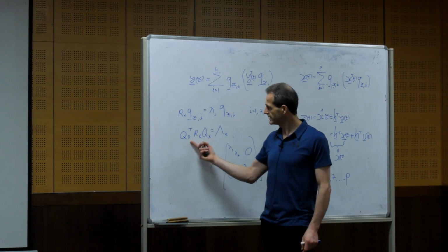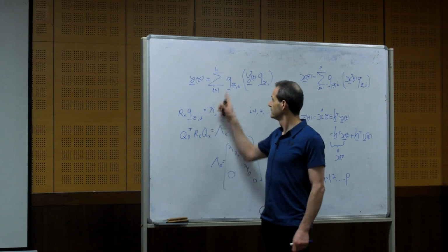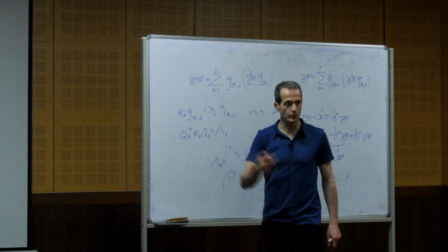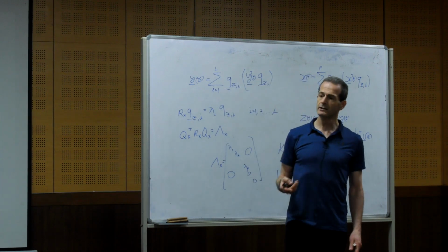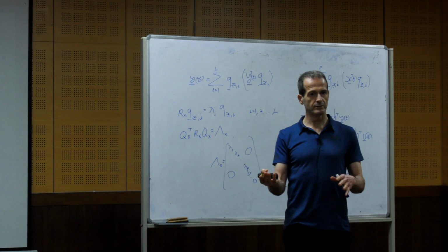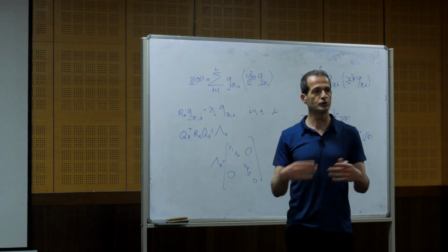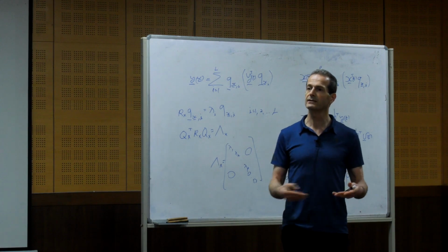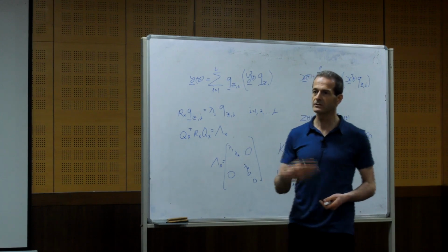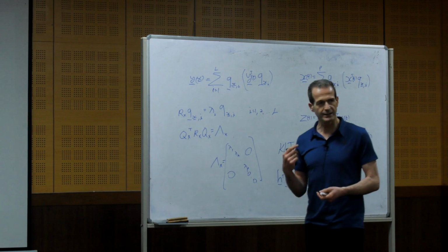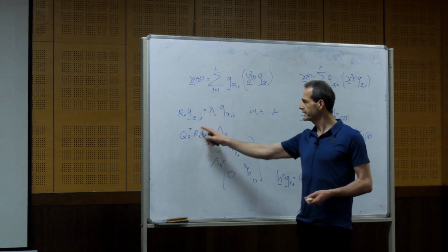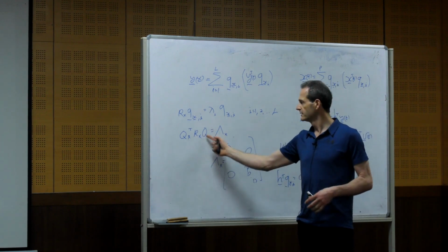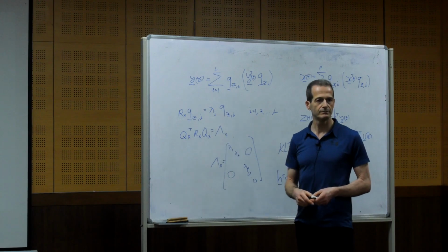And also the representation using those coefficients is high complexity. That's why the windowed Fourier transform, or short-time Fourier transform, is very useful for processing non-stationary signals, because it's much more efficient computationally than finding on each interval the Karhunen-Loève transform.